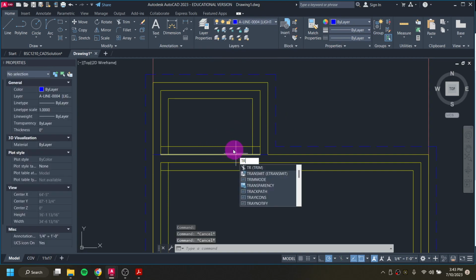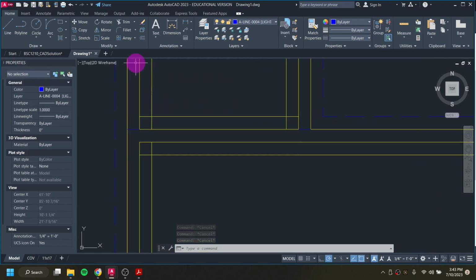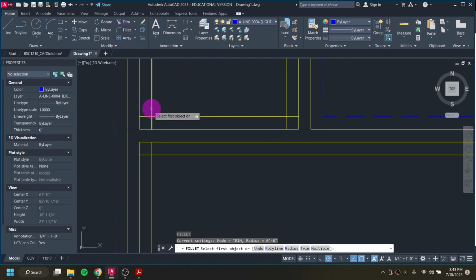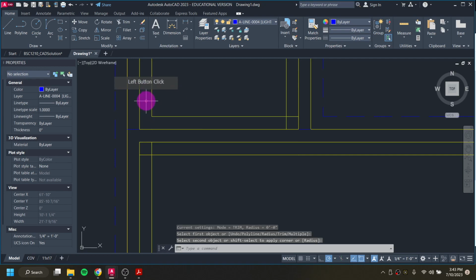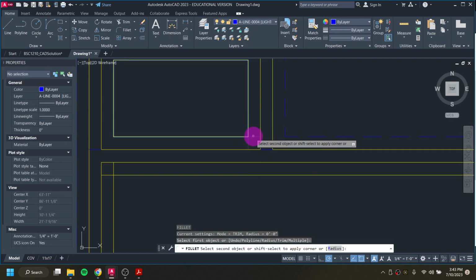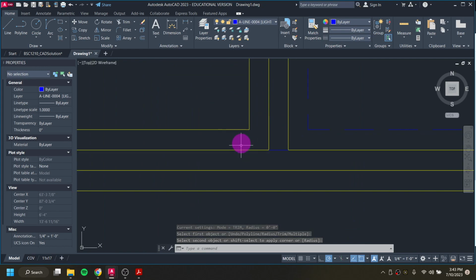I'll use the trim tool, or actually this is a case where I could use fillet pretty well. So I'm going to go into the fillet command, which is F, enter, or this button here, and I'm just going to click on this line, and it'll make a nice neat connection for us. When it comes to fillet, the order you select them doesn't matter, but where you select them does matter. So if I go back into fillet, F, enter, if I clicked on this side and this side, well, that's weird. It's actually not doing it to me. Sometimes it makes it where it's only going to keep this edge of it, but never mind, it made me into a liar.